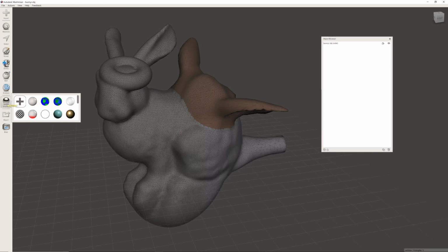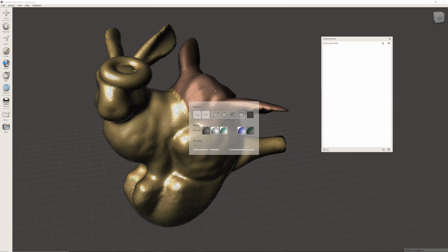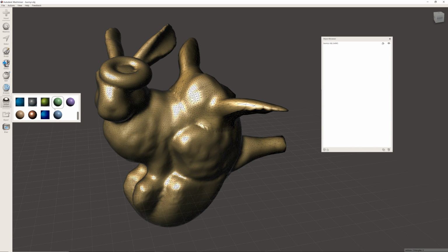You can see in our materials as well, we can have previews of materials here. And again, we're seeing different colors here because we're in the face group selection. So if we want to just see the colors, in this case our materials sort of affect the colors as well. We just activate color here, and we can try different materials on.